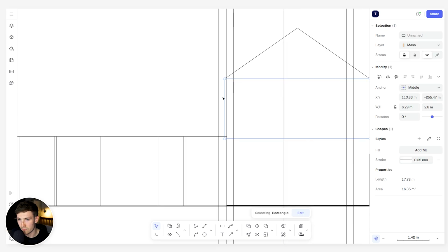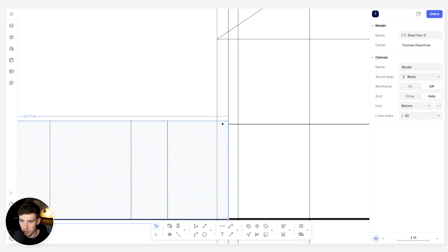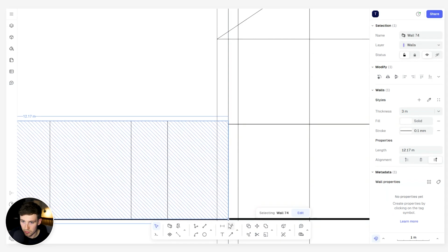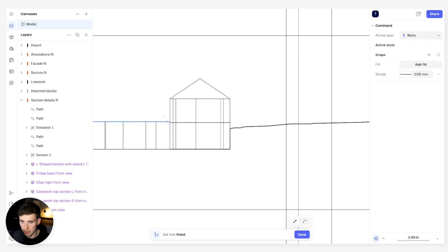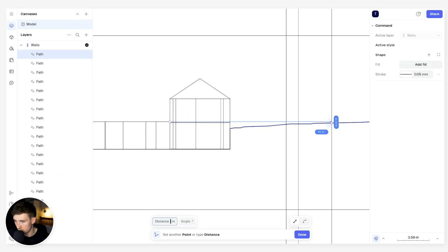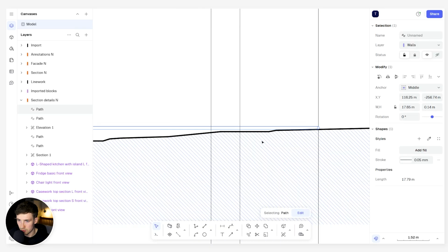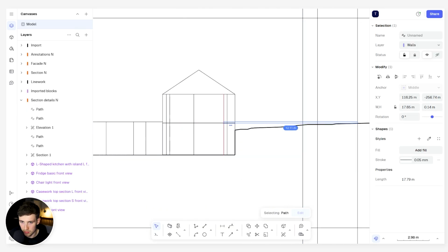And of course, this is our massing, so we can begin to adjust the massing slightly, as this won't be accurate, as this was an initial sketch to begin with. And for example, in this instance where we have this fill here, we can instead use the polyline through to indicate where this wall extends through.